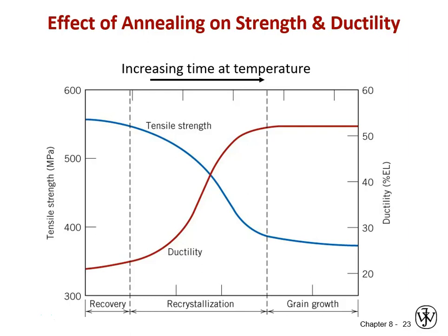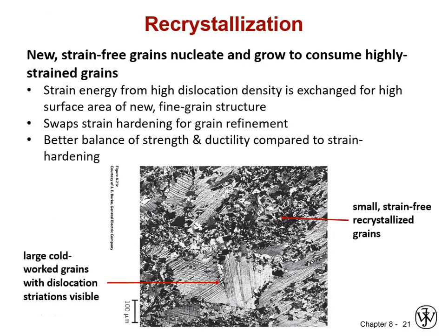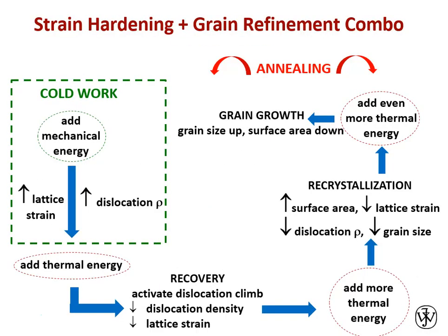This is called an annealing process, where we add thermal energy to a material to start our strain energy to surface energy swap. It's a new term. That's what's actually going on. I will flip back. Apologies for missing that term. It's new vocabulary. Every time we add thermal energy, these dotted add thermal energy circles, that is all encompassed in what's called the annealing process. And so that's basically just literally heating a material in order to drive a microstructural change. You can see that's in the red labeling.